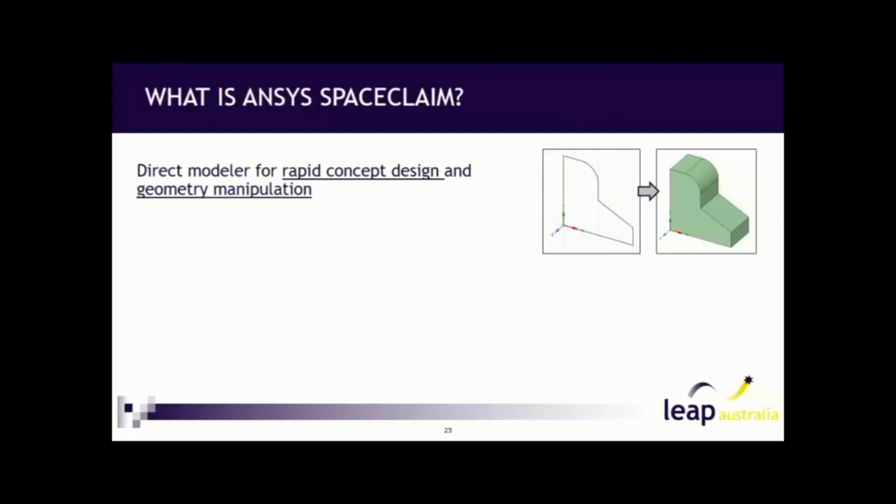Now, it's all about pre-processing. The more time you spend fixing up the geometry at the geometry level, the fewer issues you're going to have in contact and in meshing. It's going to make your simulations faster. It also means you can make everything a parameter. So you can make, say, the length of a component a parameter and see what happens, do a design of experiments of what would happen if you were to change that length a couple of times.